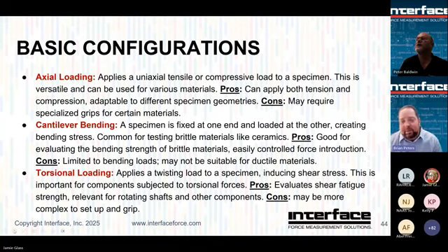Torsional testing is popular. This can either be done through an actual reaction torque sensor inline, or you can maybe do the torsional loading through a moment arm, right? Obviously, going back to an axial force input is going to be the easiest, cleanest, best way to isolate loads. It simplifies the sensor. But again, sometimes you might want to get that actual inline torsional force just to eliminate any joints or anything else impacting that. Next slide.